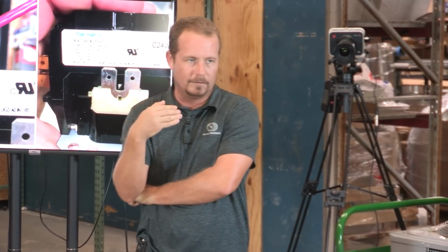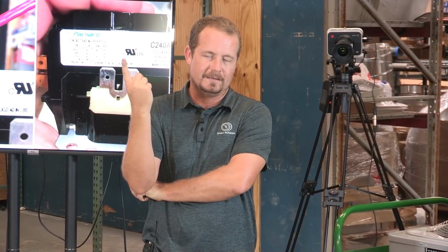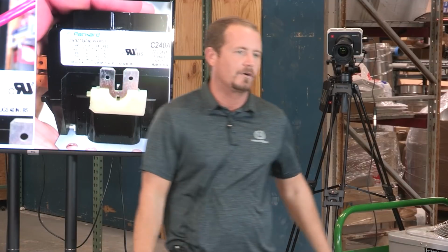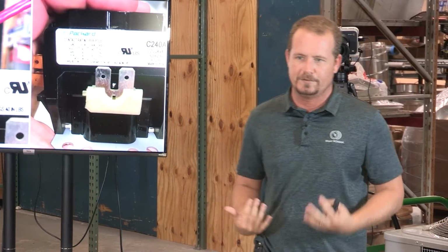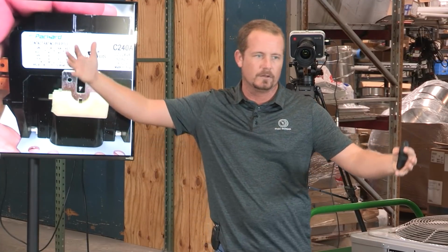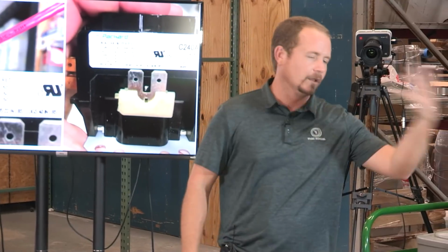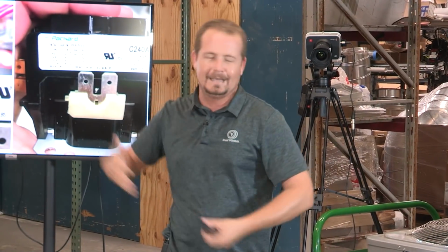So, like I mentioned, in residential, it's very rare that voltage drop is a real problem, other than two reasons. One is that there's a bad connection somewhere, like a significantly bad connection. And the other is if the power company isn't giving you the proper voltage in the first place. And that's not really voltage drop, that's just a power supply problem, right? When you get into commercial, voltage drop becomes much more of an issue because you're running these really long conductors. Now, is it possible you could have some really big custom house with a panel on one side, and it's possible.